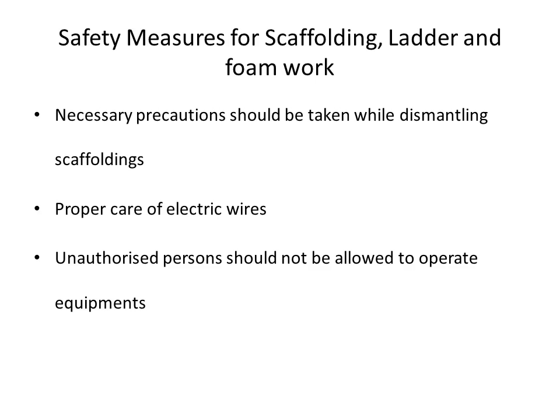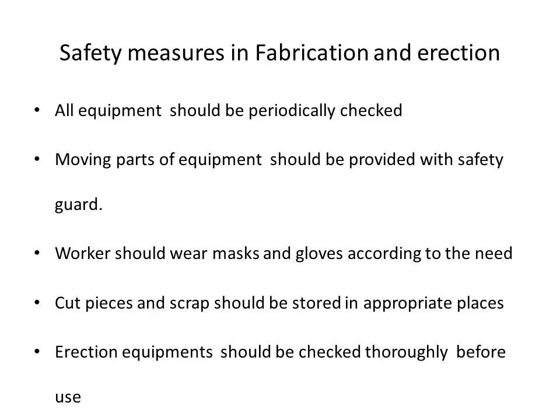Then comes the proper care of electrical wires. We have to take care of electric wires existing within 3 meters of the working platform. All the operators and supervisors should be thoroughly trained about this. Entry of any unauthorized person into the field should not be allowed, and they should also not be allowed to operate the equipment. Then comes the safety in fabrication as well as erection.